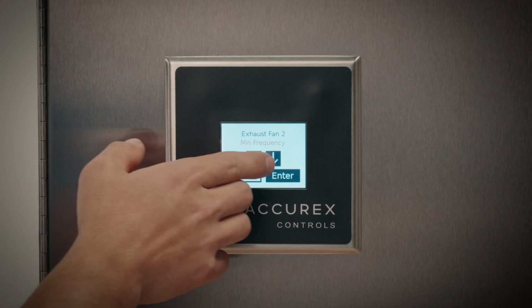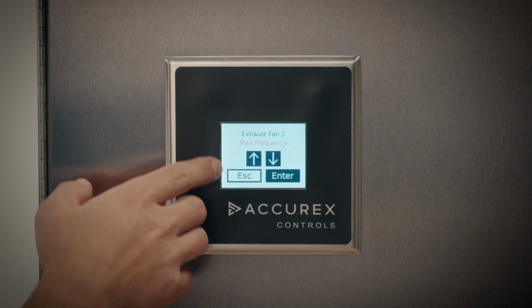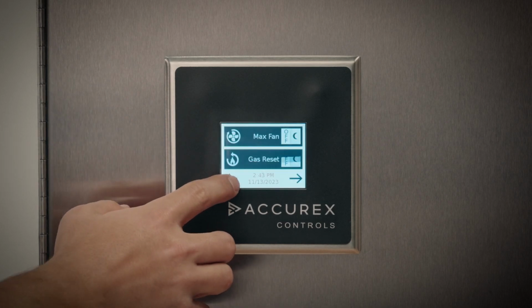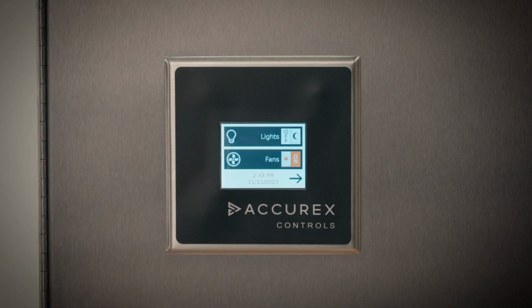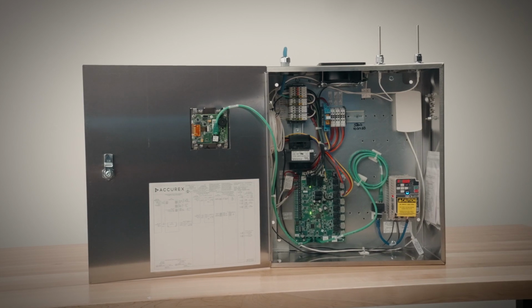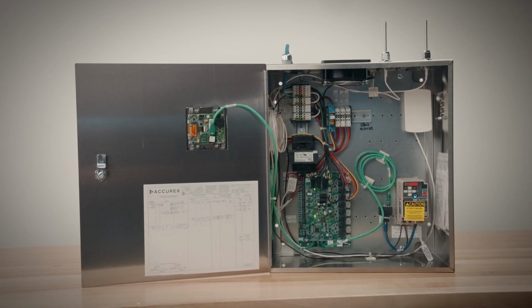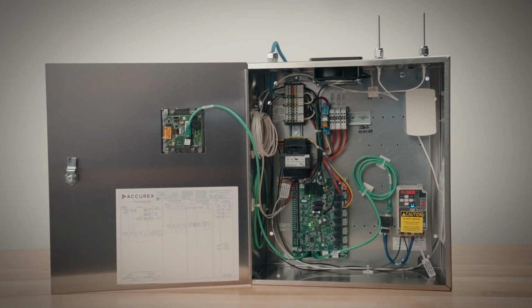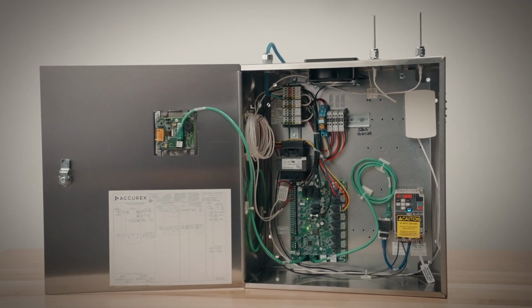In all other situations, the XKC series control panels dictate fan speed in one of two ways, and both will be done from the touchscreen of the controller and not from any drive or fan. The first kind of control is through VFDs, or variable frequency drives. Our control panel will communicate to VFDs either through Modbus, a data communication protocol, or if VFDs are remote or provided by others, through hardwired analog communication.